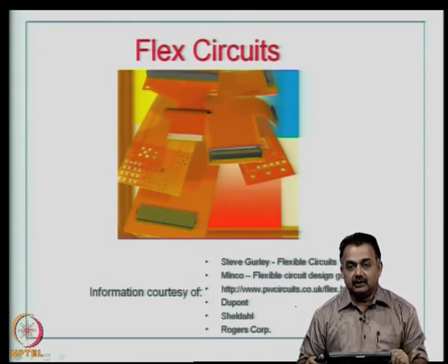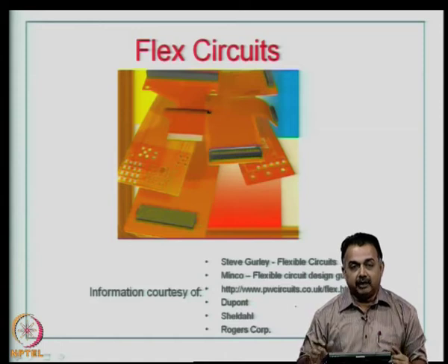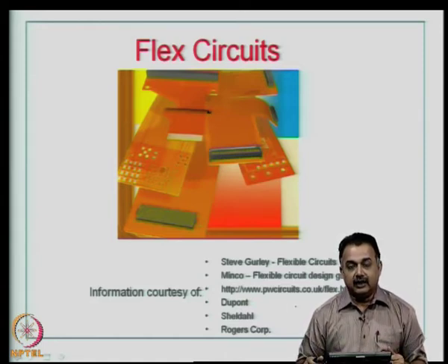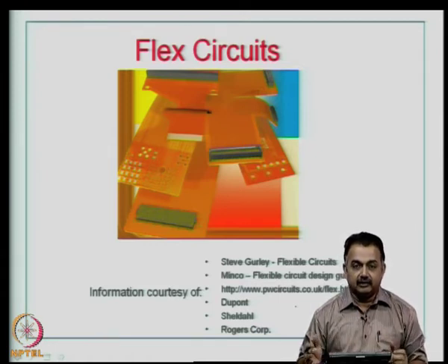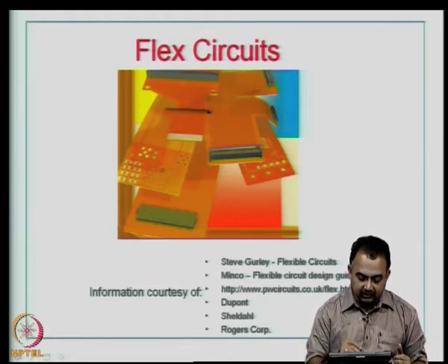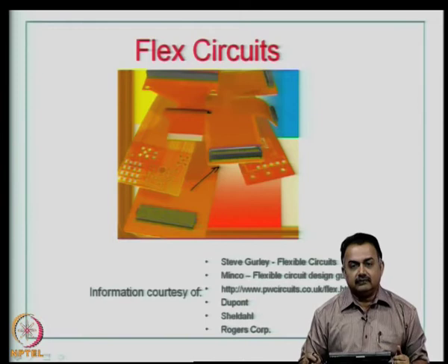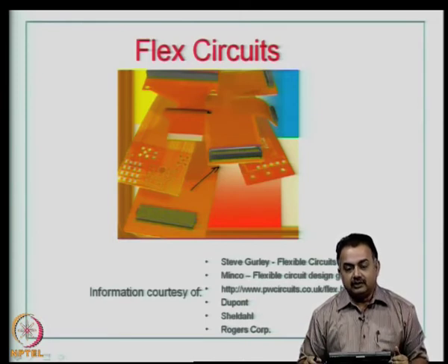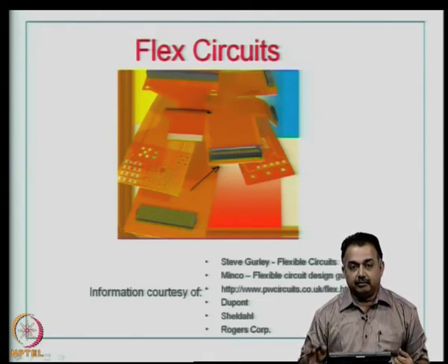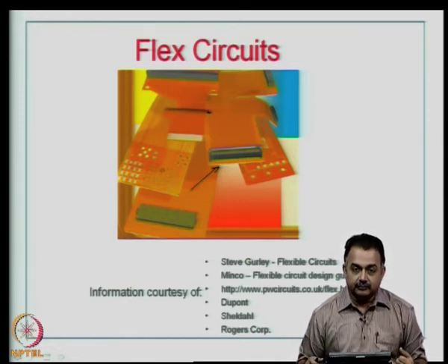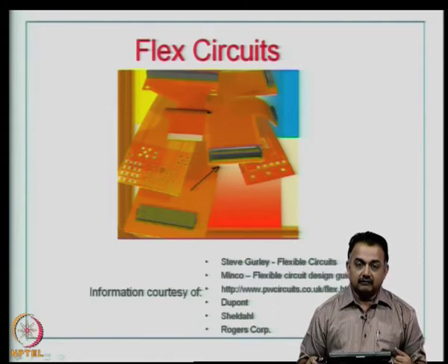It should be lightweight, at the same time high performance, but all flex circuits need not be completely flexible. It can be partly rigid, partly flex. So, you can have sometimes a completely flexible base or a circuit, or it can be a rigid flex. Some ends, as you can see here in this picture, some of the ends of the substrate can be rigid, the body of the circuit can be flex. So, it depends on the design, it depends on the mechanical product and the enclosure where this particular design goes into, and accordingly you can devise a flexible circuit.